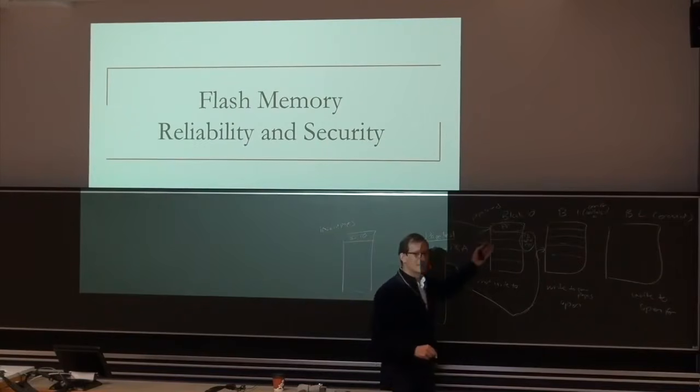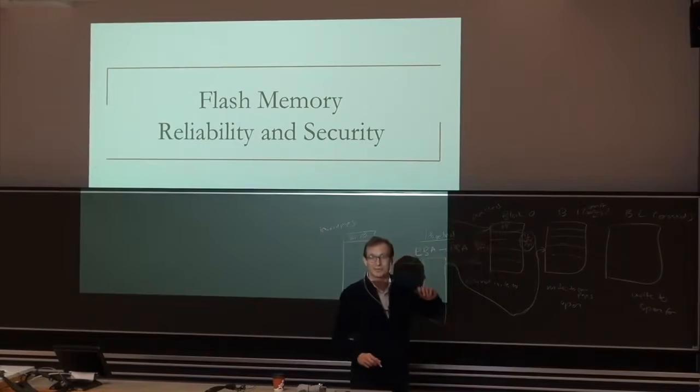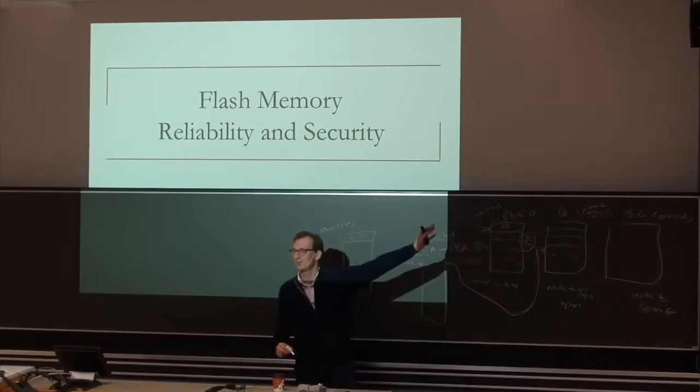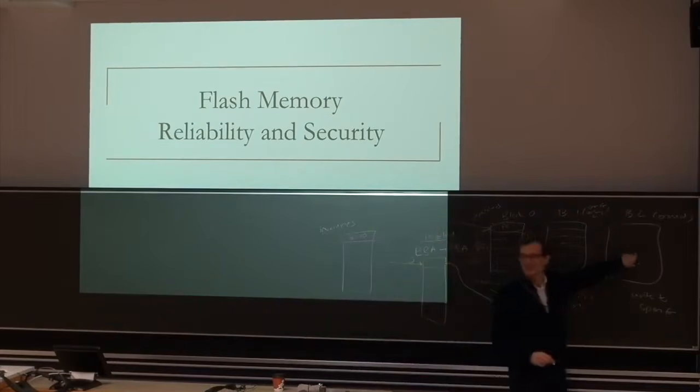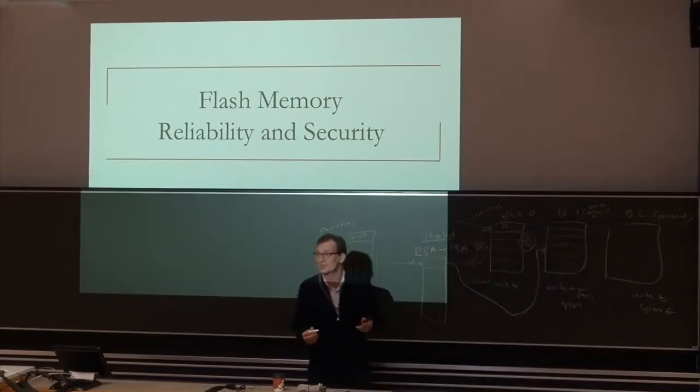Sometimes, this depends on the algorithm of the controller, but sometimes what the controller says is, heck, I don't want to waste a lot of this, so I'm going to move those 56 pages to a block that I erased. In the background, I'm erasing stuff because I'm smart. Make sense? So that's one way of doing it.